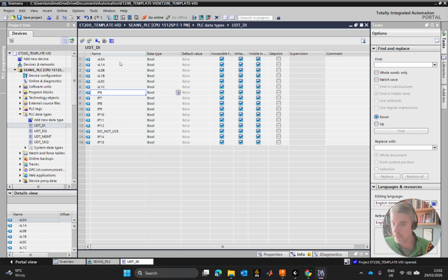Then I will give another input, and what I typically put onto this one is my pressure sensor. It's not always called for, but I like to keep it in there, for the fact that you might have a pressure build on your PLC. So let's make sure that we have an input in our template that is going to monitor that pressure build, and send a trigger when the pressure is at the specified set point value.